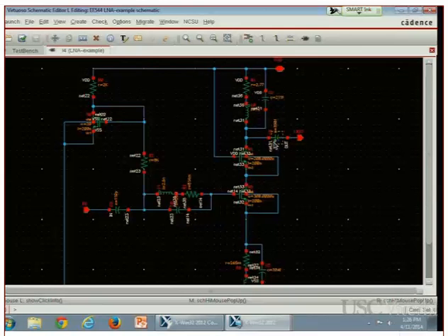So basically what these capacitors are designed to do is let the AC signal in. Since the voltage across the capacitor can't change instantaneously, a high enough frequency signal coming from the input will be superimposed onto this DC voltage right here. Okay, and the same thing here. This is basically just to isolate this circuit from what comes before and what comes after it.